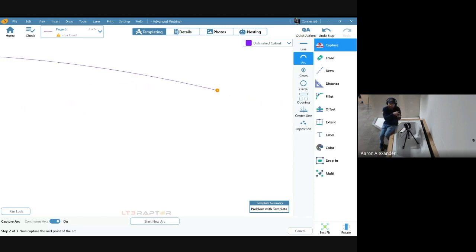I'm going to check that tangent when I create the next arc. So I'm going to shoot the middle of this little one here, and then I'm going to shoot the next pen mark I got, marking my tangent. And now I zoom in, and see how good I did there. You see that. That does not look that good, right? I bubbled that thing out. Typically, that means I tried to shoot my tangent before the arc actually started. So I created that little arc larger than it should have been because I didn't hit the tangent right there.